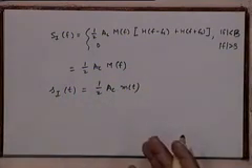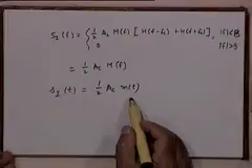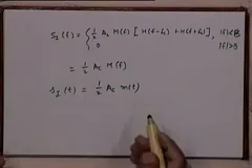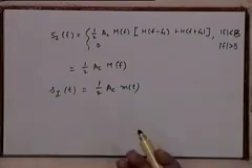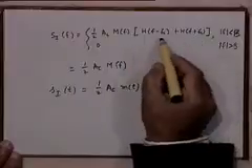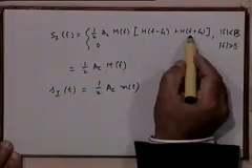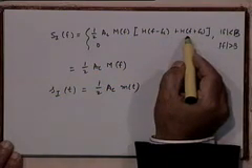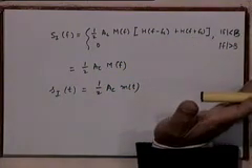So once again the in-phase component remains the same, whether it is a DSB-SC signal, an SSB signal, and now a VSB signal: the in-phase component remains proportional to the message signal m(t), and that is the reason you are able to recover it through coherent demodulation, right? And that was made possible because we had satisfied this constraint that this plus this must be independent of f, must be a constant, right? So I think everything falls in place.